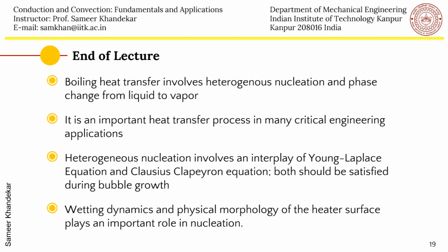And wetting dynamics and physical morphology of the heater surface play an important role in nucleation. So you will see later on that actually rough surfaces are good because many nucleation sites get active. And if you have a very smooth surface, then the boiling superheat, or the wall temperature which is required for boiling to take place, is rather high, and therefore not good for heat transfer applications.